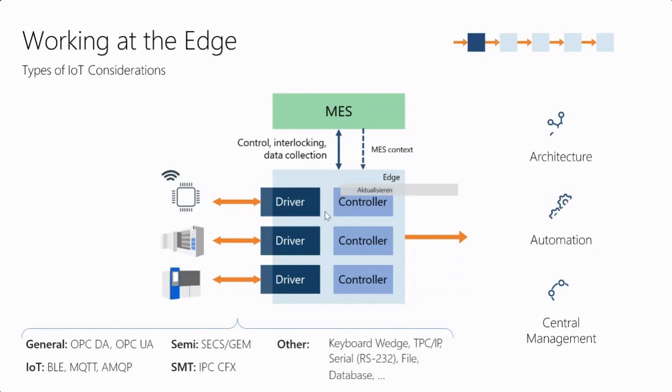And of course, there are other protocols for the semiconductor industries like SECS and GEM, the Generic Equipment Model. This is a famous model. They use this to communicate and get device data when we produce. Again, we use different serialization like the RS-232 protocol to connect it to the internet network. So you use an RJ45 jack and serial communications to have inter-data capabilities. This is how we set up the edge processing.